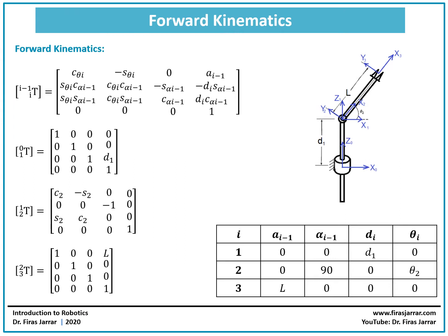Here we're going to start with the forward kinematics. In the forward kinematics, first of all, we need to determine the DH parameters. So starting with the link length A, starting with A0. A0 represents the distance along X0 between Z0 and Z1. Z0 and Z1 are coincident or parallel to each other along the same line. So A0 is going to be 0.